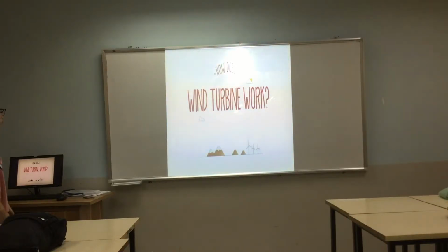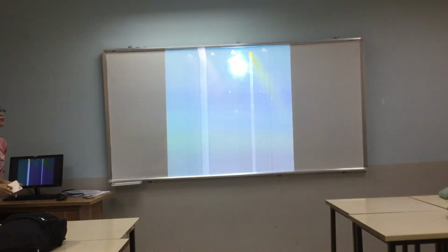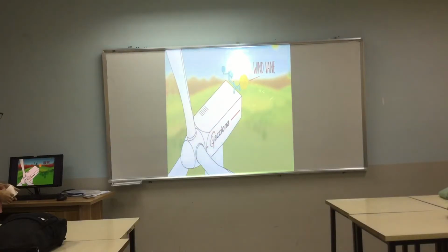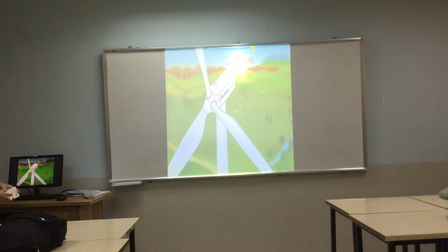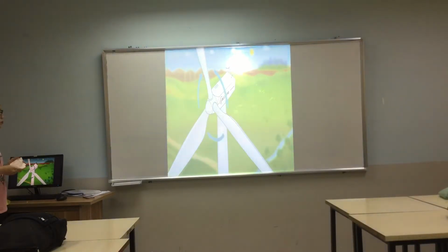You've probably seen a wind farm, but do you know how wind force is converted into electrical energy? We are going to show you how a wind turbine works. Each wind turbine has a wind vane at the top that indicates the wind direction. This allows the turbine to rotate on the tower and face the wind. The blades also rotate on their axis for maximum resistance. Wind force, that is, the kinetic energy contained in moving air currents, spins the blades. These are designed to fully capture its energy.